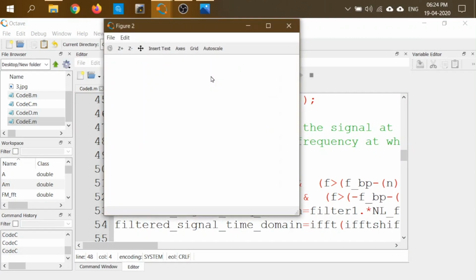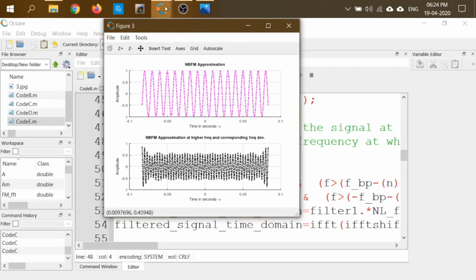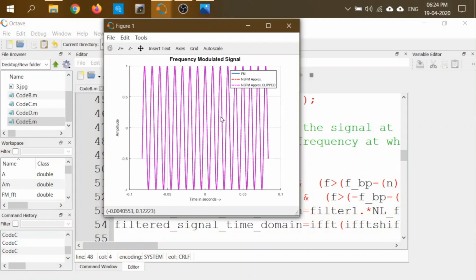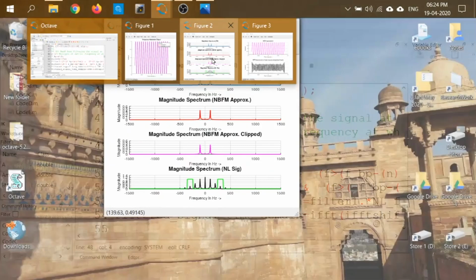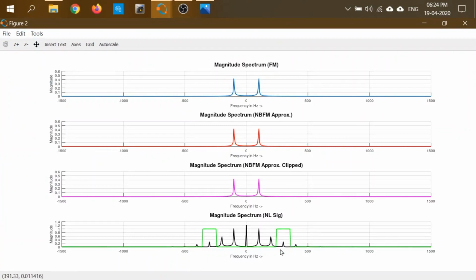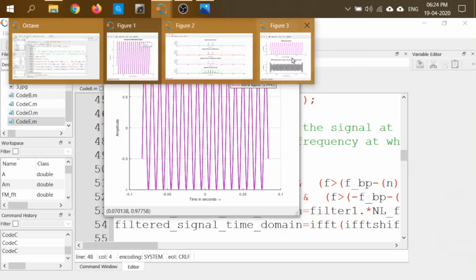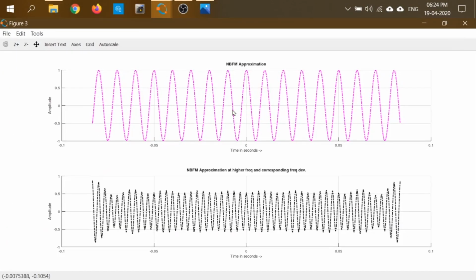So an application of this, let's see the time domain picture first. In the time domain, you can see these are perfectly matching because kf into mt is not tampered with. In frequency domain, you see that the filter has shifted to thrice of omega c, and here actually you see the filter width is also increased correspondingly. Right now, we can see it in this recovered signal form also. So corresponding to one cycle, you will notice that there are three such spikes corresponding to one cycle. So the frequency of this has become thrice, although the amplitude variations are there and we have discussed that they can be dealt with. So it can be done there.